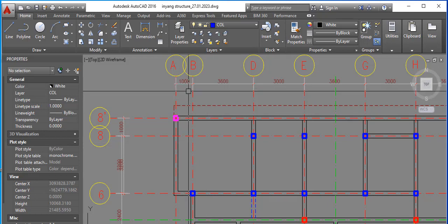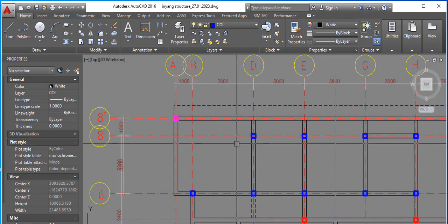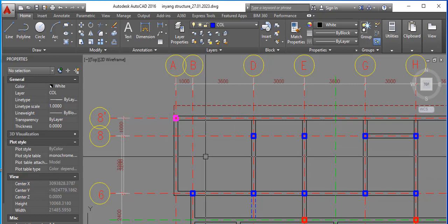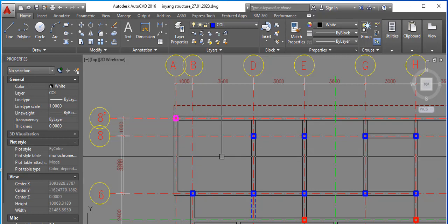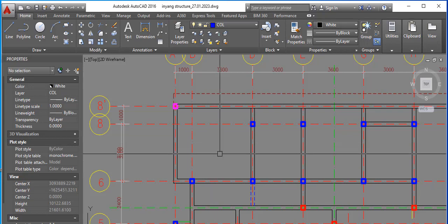So if we see this, there is about 4.6 meter. It means one of the wood you have to cross, you have to connect it here. So I would advise that you break that span so that the wood you'll be using can easily rest from one beam to the other without joining them. So with that, it will make your roof very strong.